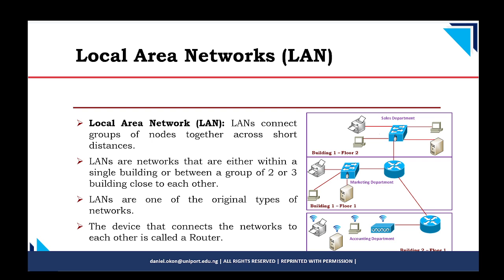So the cables coming in from here must always go to air condition because the cables have to be very thick. This other one now, maybe the one for sockets. So from this single box, the electrician already knows that all air conditions must connect to that side. All lights and fans must connect to this side, and all sockets to connect to the downside, because this is a distribution box.